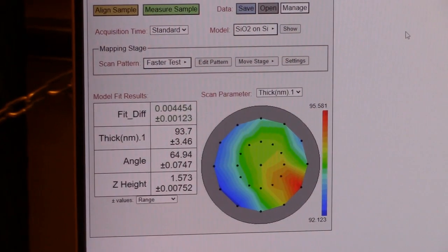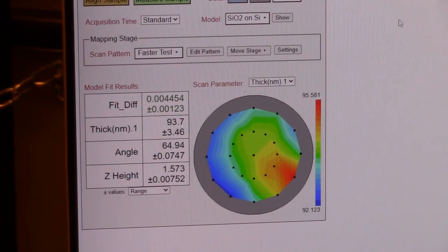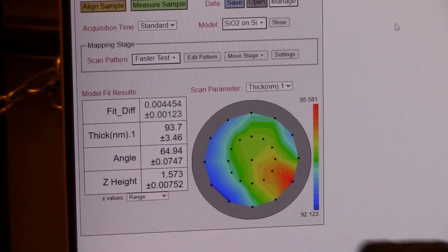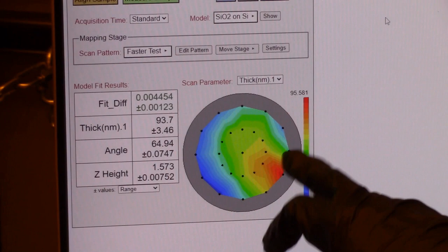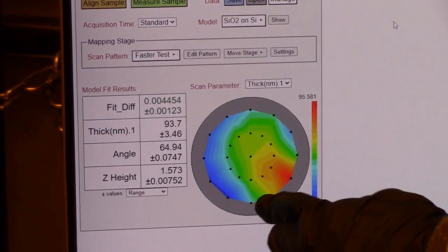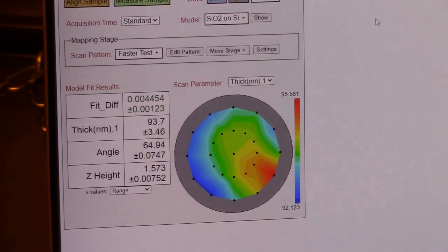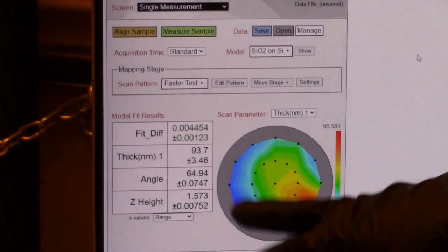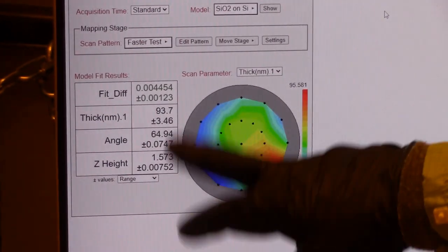But it is always a good idea to measure the oxide after you grow it to compare any experimental effects that might happen. A quick wafer uniformity map tells us that it is slightly thicker towards this edge as opposed to the other regions, though there's not a huge difference in thickness. This could be due to flow gradients, which is probably the reason why you're seeing a slightly thicker film right at this edge as opposed to the rest.